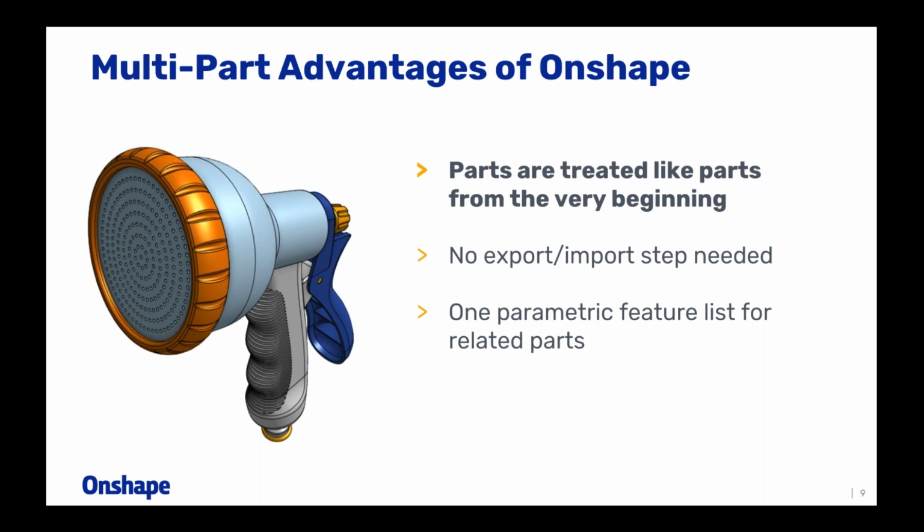If I'm designing a complex relationship between multiple spur gears, maybe, but not if I'm just defining, I just need to input X amount of spur gears and drop them into my assembly at random. If designing around the spur gear location and all of those details is super critical, then maybe putting those together in a part studio makes sense. But I tend to lean towards those being broken out.